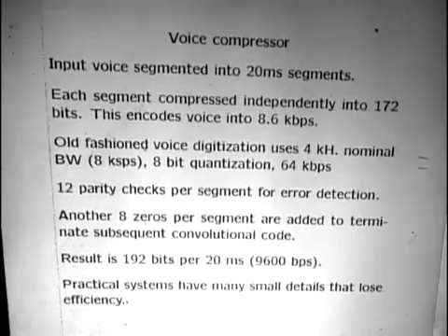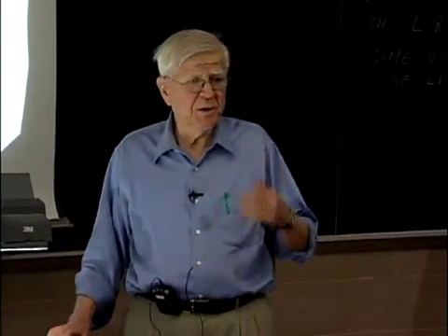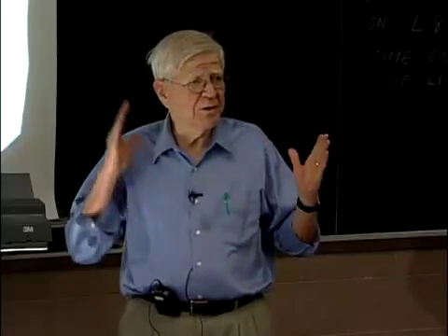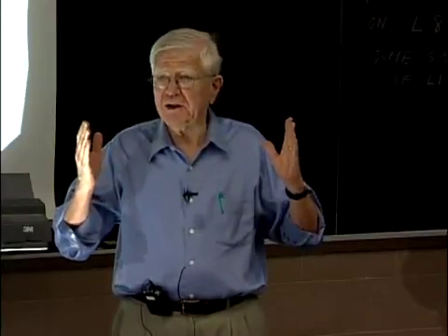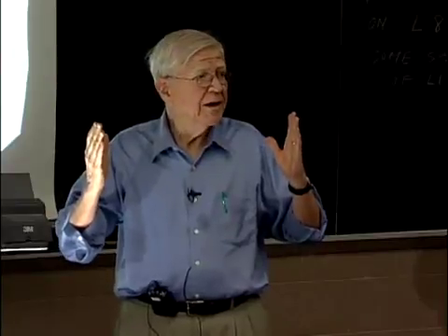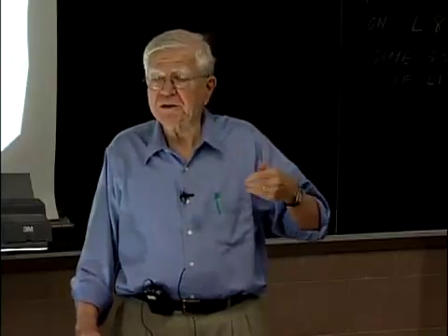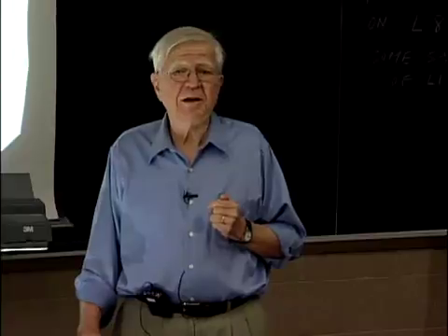Now that might not sound like much of an achievement, but if you think about the old-fashioned way that people used to encode voice back in the time when they were first doing digital communication, what you would do was think of the voice as having a bandwidth that went from about 400 hertz up to about 3200 hertz. You would then view it as a baseband waveform from 0 to 4000 hertz. If you were going to try to sample that waveform, you'd have to sample it 8,000 times per second. And if you want good quality, you then have to use a large number of bits for each sample. So the standard thing was to use 8 bits per sample. That gave you 64,000 bits per second in the old-fashioned way of doing it.